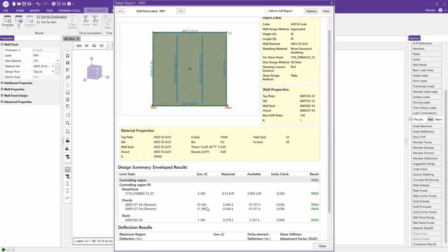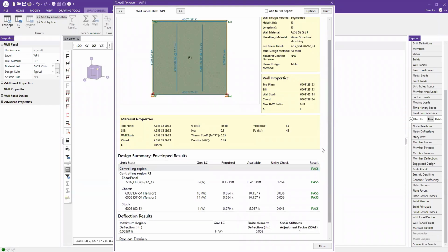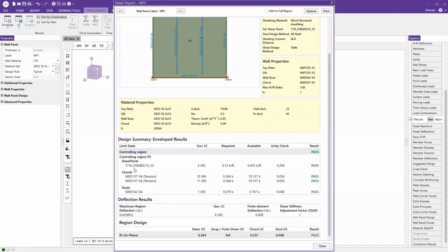So this makes a difference because some of those are earthquake designed. So we would have seen an E listed here if this was governing by an earthquake versus if it's governing by wind. So it's something you want to pay attention to. I actually think if you are running a model of any size, you want to know what is governing. Is it earthquake or wind? Because that's really going to help you understand why this is being selected, why other ones aren't, and going down that path. As you go down design, you're going to want to make sure you know if there's a better one selected, or if you understand that earthquake versus wind, that's the first step.